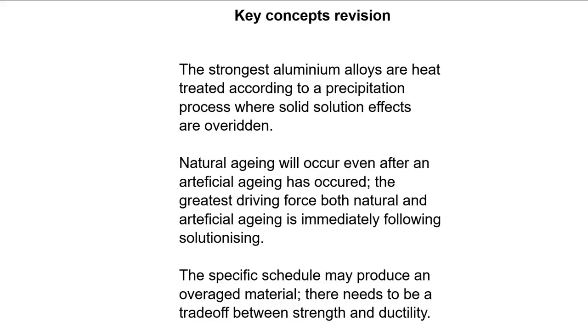Due care and attention needs to be paid to assessing how much natural aging can take place in the intervening periods with these heat treatments for these alloys, and will also have implications for further processing, such as welding or even in service conditions. In some circumstances, the alloy will continue to age in service, even after going through a full artificial aging process.